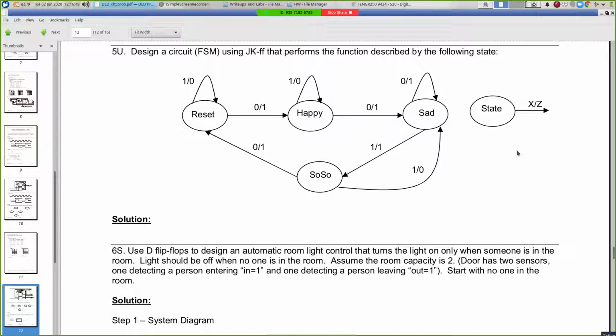So about a quarter of the circuits that I saw for this and the analysis that I saw called their input A, and they called their flip-flops X and Y. And that's very confusing, because the input is supposed to be X, and if you use X for the name of a flip-flop, then somebody reading this is going to think that that X is the input value, and it's being used as a flip-flop output, and it's just going to be all kinds of mismatch with what you're trying to do here. So that was one thing.